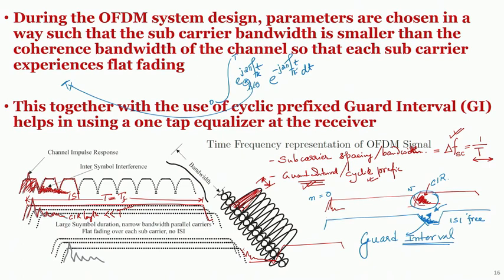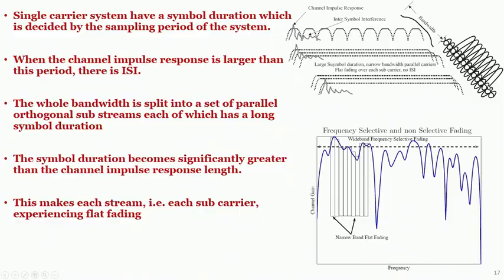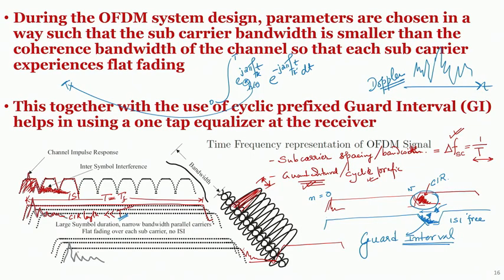So, we cannot avoid it, and hence it is better to choose a guard interval, a loss which you can't help, but then there are mechanisms which people have been working on to reduce this guard interval. We will get an opportunity to see that. And now, coming back to the other important thing, if we make this T very long, then because of mobility there is a factor called Doppler which comes into play, which we will see again later. Because of Doppler or because of mobility, we have said that the channel fluctuates in time. We also require that the channel remains constant in this entire period.